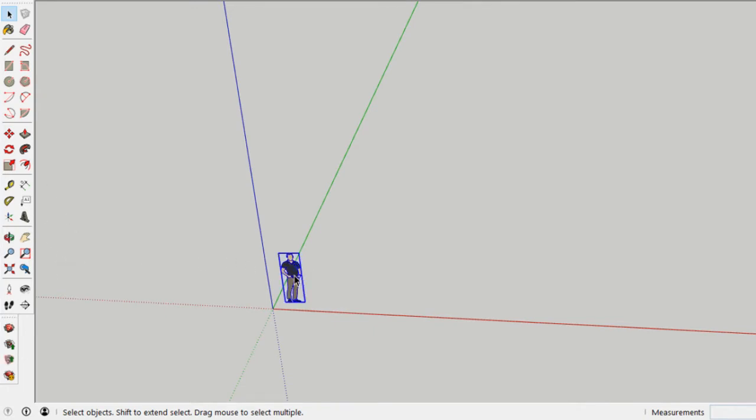But let us get more into this flat Earth thing. Let's get rid of him first. To make a curvature model, you need to go to this arc tool: draw arc from center and 2 points. And if you see down here, 12 sides. This is not enough. At least 36 to make a smooth model. Enter.